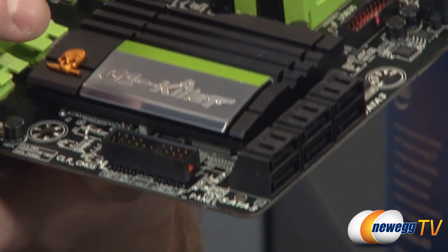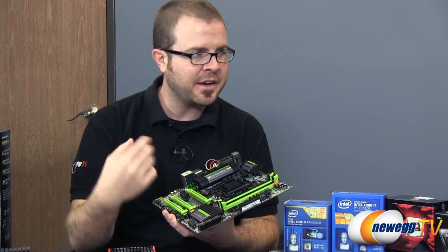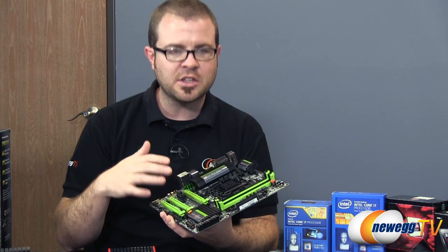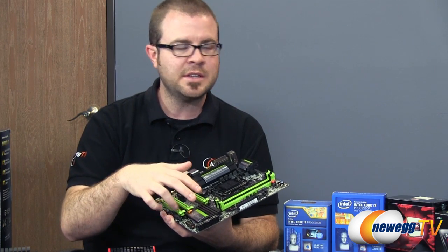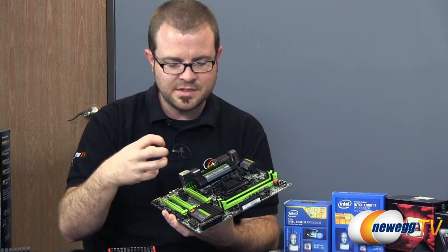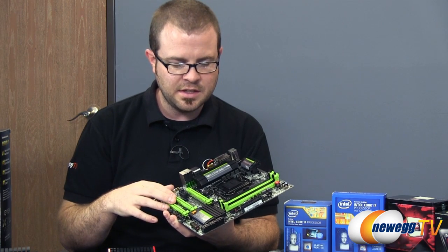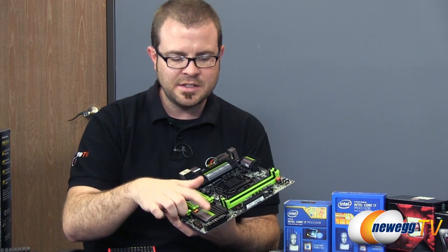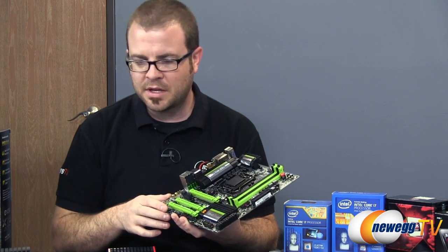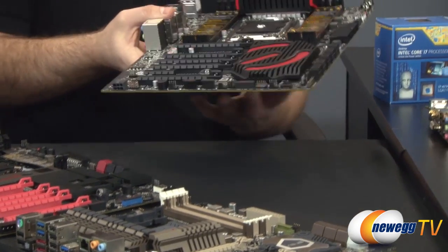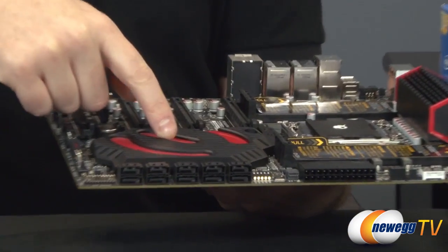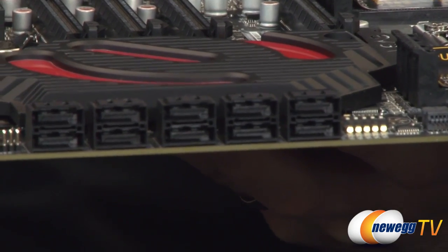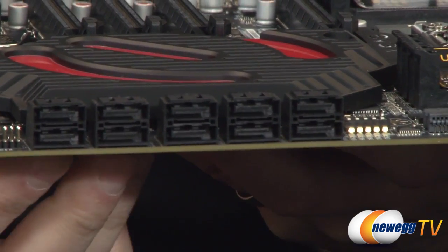Apart from a chipset on a board, you might have other chips that are integrated onto the board. Chipset is a larger term that refers to a larger chip that's on the board, and it's more integral to the motherboard itself and the performance, versus add-on chips. So for instance, this chip controls 6 serial ATA ports, but I'm pretty sure there are other boards out here which give you additional serial ATA ports. For instance, this motherboard here, which is an X79 chipset for the Socket 2011 Enthusiast platform, has 8 serial ATA ports.